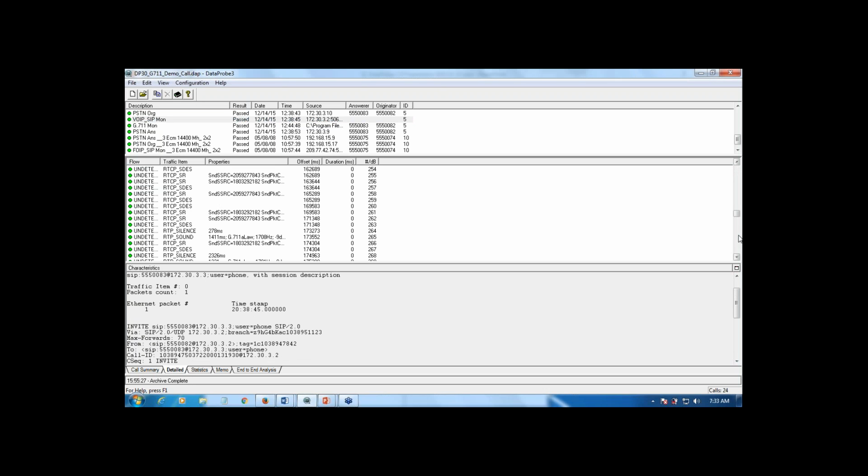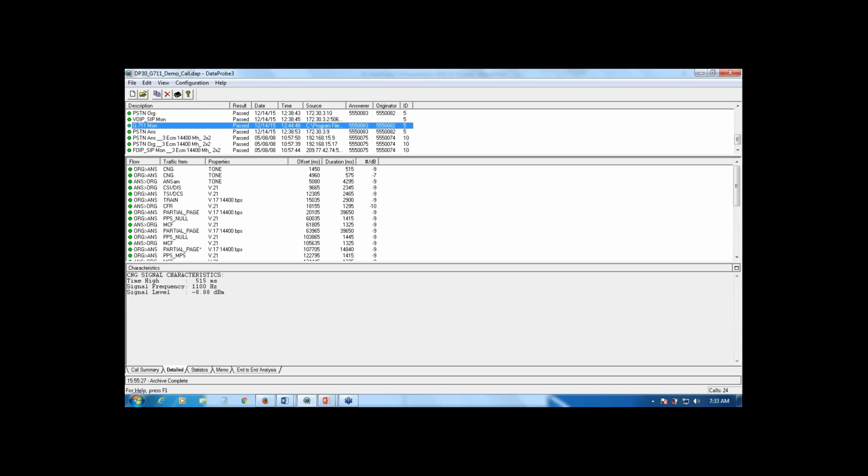Literally, these are your G.711 messages, and if you wish, you can directly look at this same information with Wireshark. We'll export a PCAP file that has this in it. You can look at it from Wireshark to see what it has to say about the network exchanges. You can look at it with DataProbe to see that the actual information was being exchanged for the fax call. What was contained within this is a G.711 call, which again was digitized analog data containing T30 messages.